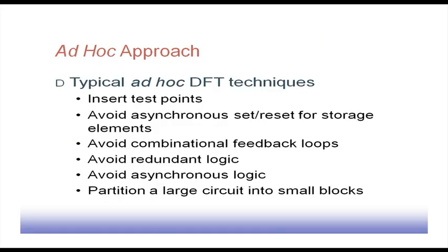So, we will start looking at the ad hoc approaches. Typical ad hoc techniques are like this: insert some test points, and avoid asynchronous set/reset for storage elements. If there is asynchronous set/reset, then when we are designing a test pattern, all of a sudden a reset pulse may come to the flip-flop and the flip-flop gets reset. Naturally, that cannot be accounted for in the testing process. So if my design can be constrained so that I do not have this asynchronous set/reset, then it is better.